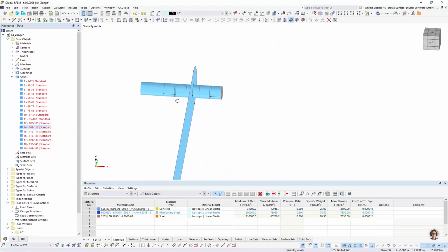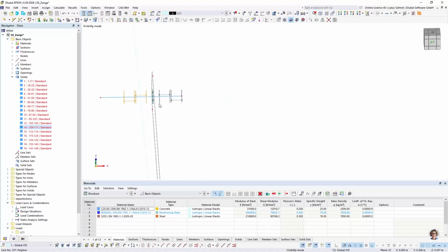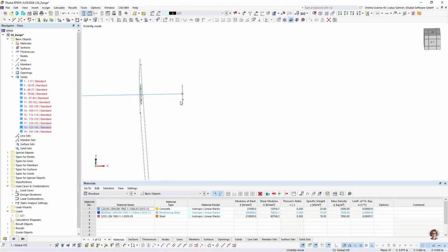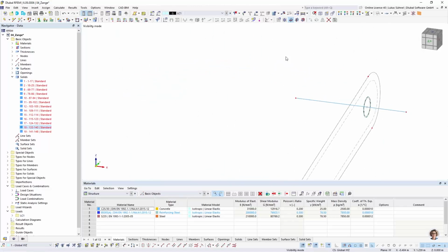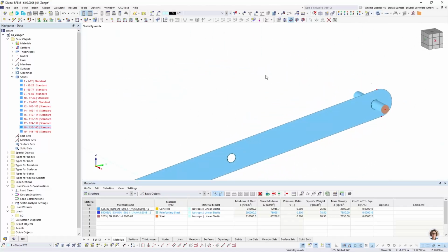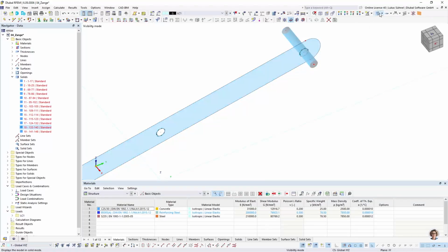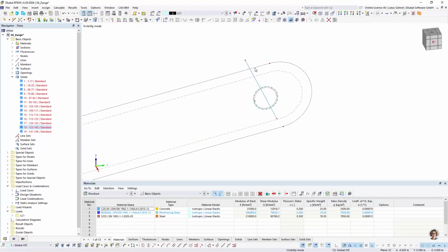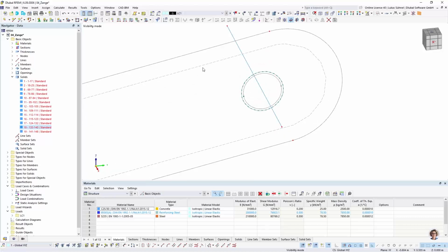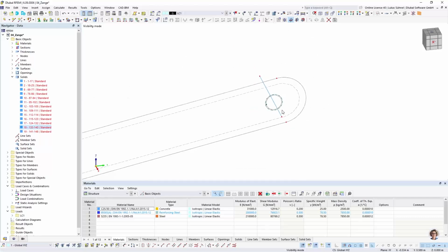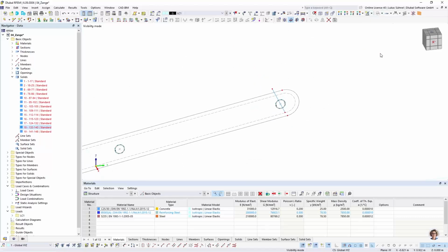with its boundary lines. And then we can change the rendering. There are some lines remaining. I can simply delete them. And I have my simplified surface and beam structure. And concerning the connection between this bolt and this metal sheet, I would use maybe a wheel of members, of beams or coupling members, to create a proper force transfer. Yeah, this would be my simplified approach for that model.